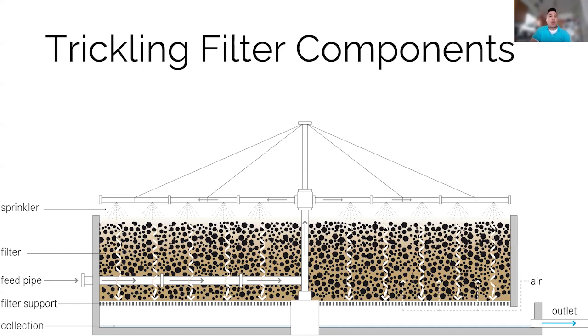We have the media, we have the distribution system, there's the containment structure, and then that under drain. So that makes sure that we have the ability to get the water in, the water is distributed, the water is treated, the whole process is housed, and then also the under drain removes the effluent as it is treated.